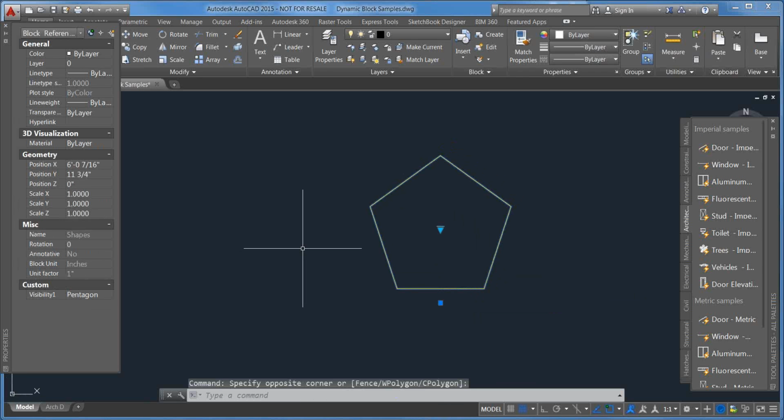We got a little stack of questions here. Okay, let's take a look. So Jennifer, first I'll get to Jennifer's comment here. You can also use these blocks to hide objects behind them using draw order and hatching in the block instead of cut and trim. So that's a good comment, Jennifer. Appreciate that.